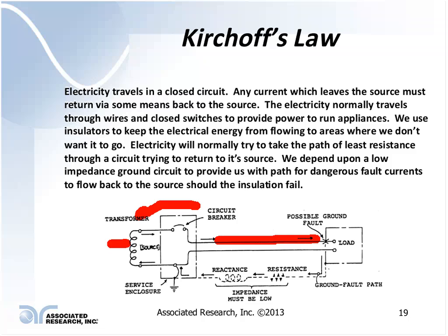If the insulation fails and that shorts out to the enclosure of the product, now if my ground circuit is intact, what would happen? Well, this ground circuit should have a low enough impedance that it will allow this current to flow back to the source, back to ground, and essentially cause my fuse or circuit breaker to open up. That's what should happen.